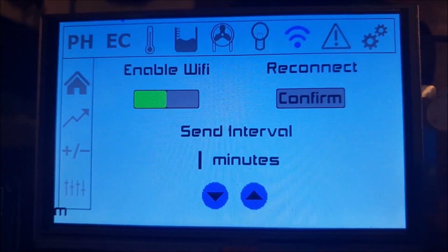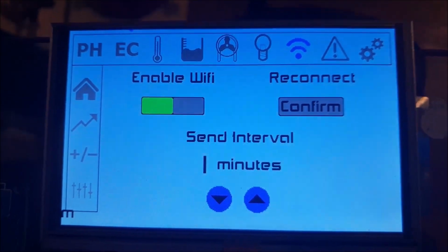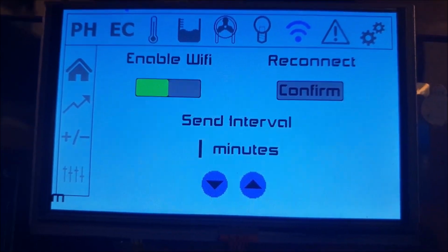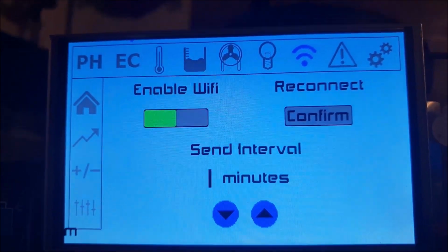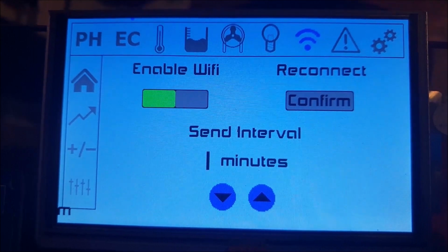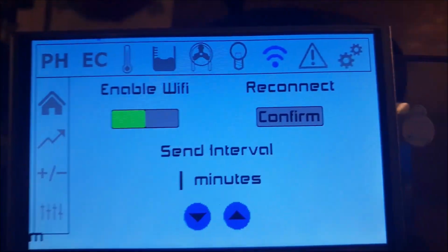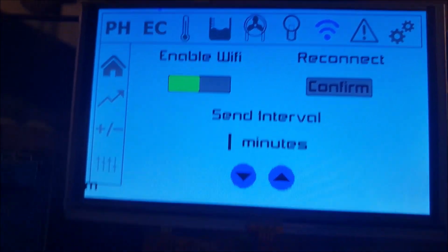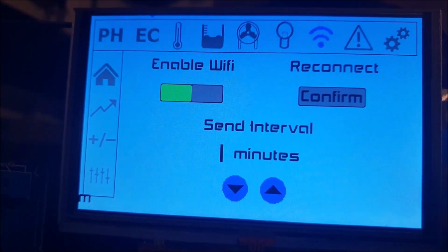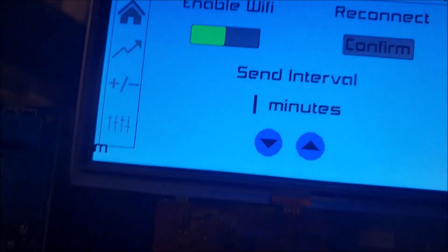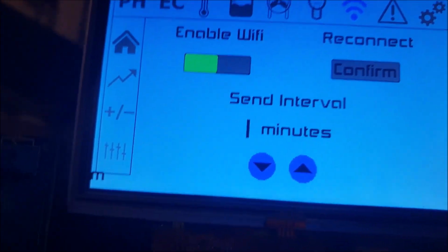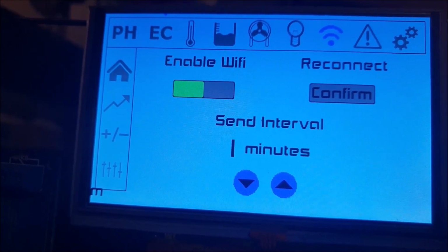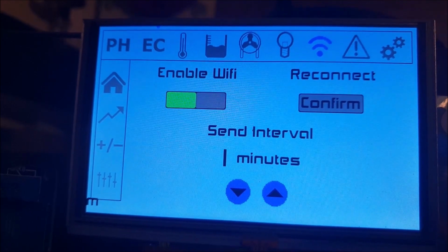This is just really simple math. It's a lot more to it than this. But basically it takes the current reading and then the next reading, works out the difference between the two, and then adjusts the dosing amount in mils respectively. So if it dosed, and this is within 0.1 precision, there's 160 blocks. So if it saved the value at 5.1, and then later down the line the value equals 5.1, it can say, if you're at 5.1, I know for a fact that it's going to adjust the reading by 1.